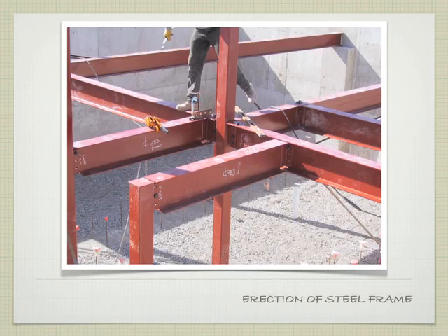Similar, we can see a lot of the details that I've just talked about. Each one of these pieces is labeled. It has a center point, so we know where that is. All of these are prefabricated, and they're bolted into place. Not all of these have every bolt in. Here's a good example. There's one bolt holding this here. We don't have the rest of the bolts inserted yet because we're still working through these particular pieces. Oh, here's another good example. That's a come-along. This is like a type of winch. It's attached diagonally from here across, trying to adjust this particular piece and get the building square the way you want it to. Does that make sense?